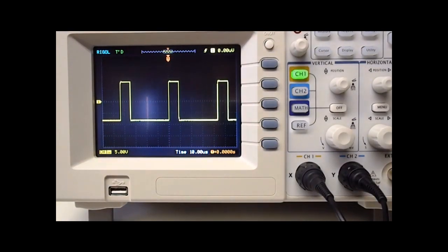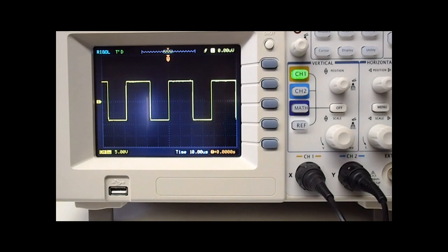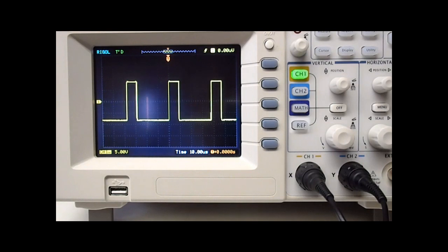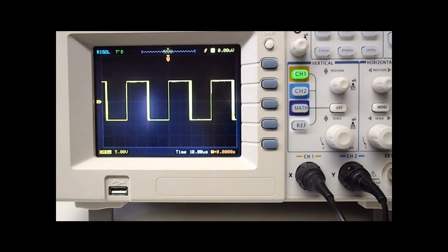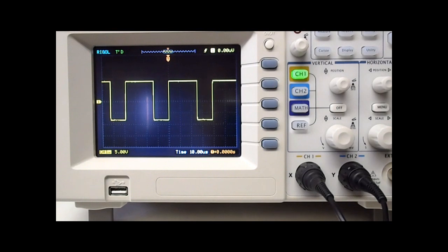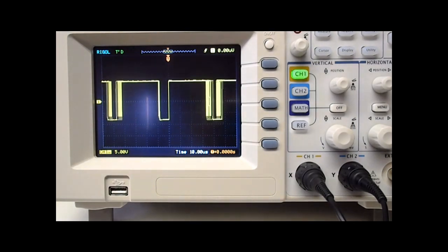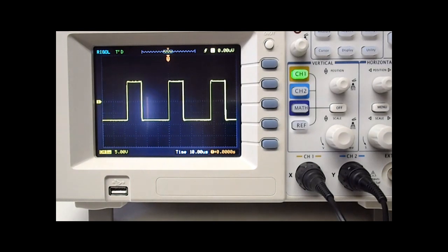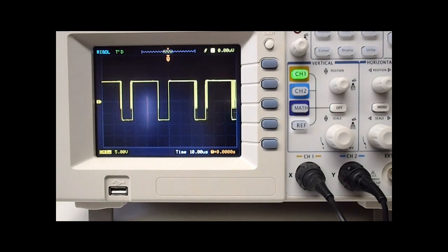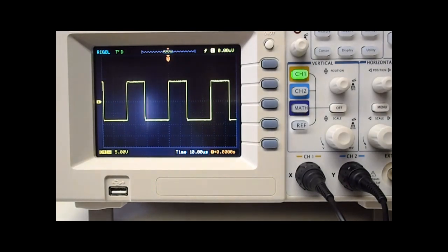Now there's a lot of things to take into consideration when you're buying an oscilloscope. The first one would probably be the type of oscilloscope. There's two main styles of oscilloscopes nowadays, which is the analog and the digital storage oscilloscope. Now I highly recommend starting off with the digital storage oscilloscope, as they're able to do a lot more functions than an analog oscilloscope, such as actually take measurements, addition and multiplication, and do actual math functions. So an immediate feature, I do recommend them, though you can learn a lot from an analog oscilloscope because they don't do all those things for you, so you're required to think a lot more for yourself. But starting off, I think a more useful tool in the long run is immediately the digital storage oscilloscope.